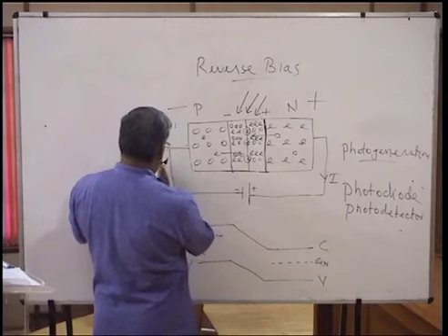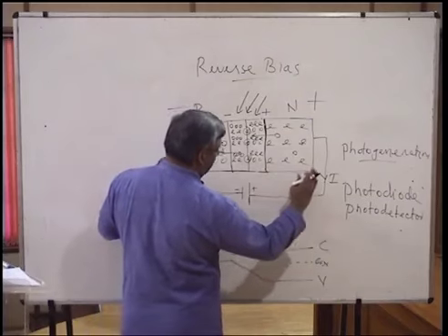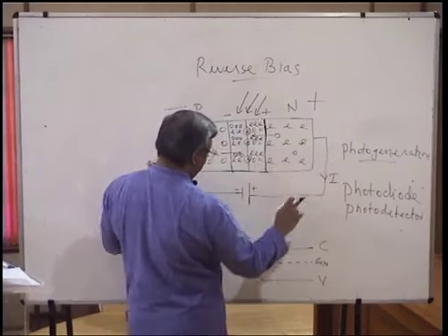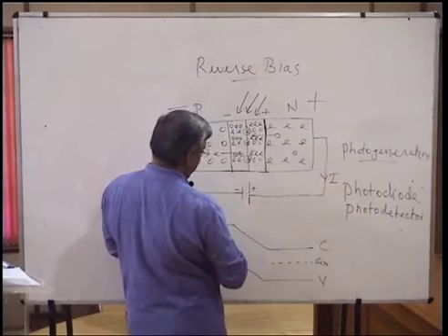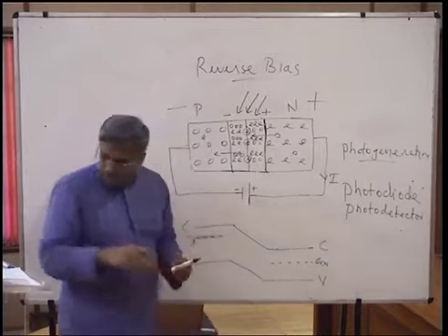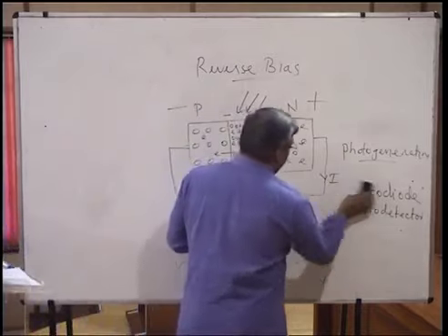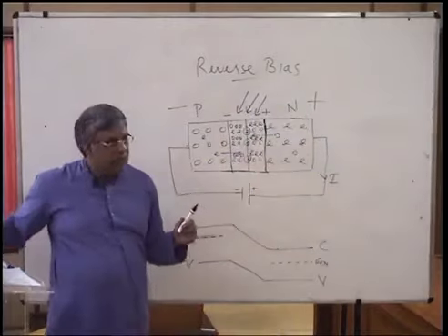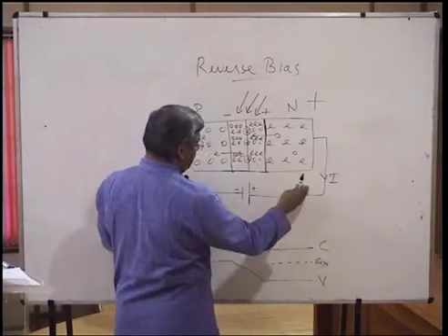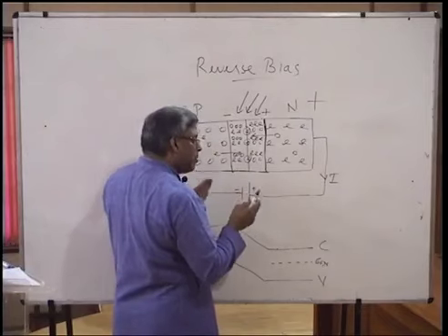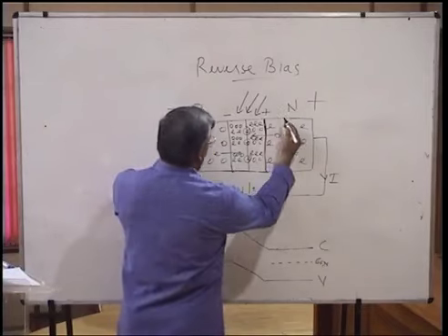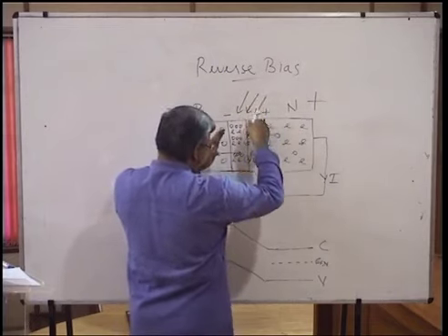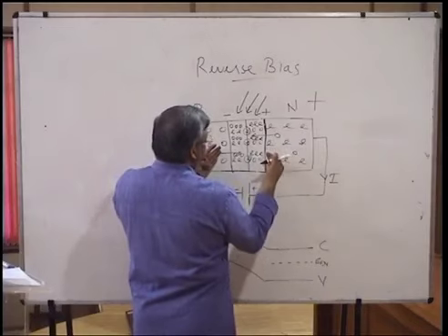So you have a transmitter, the channel, and receiver. So this completes the cycle of communication based on photon. Now, we should also see that in these photodiodes, this particular depletion layer is already expanded a little bit due to the reverse bias, but this may not be sufficient. You need to broaden this area as far as possible, because light is supposed to fall on this depletion layer. If it falls anywhere else, it does not create this effect.